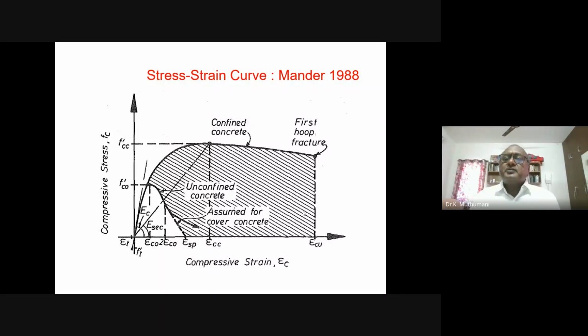And that is what is going to matter, because one thing is very clear by now, that the load that is going to come, and because of that the stress that is going to come, is larger than whatever you computed. That is the first step. The second step is, the only way of taking care of it is if the concrete has a higher strain capacity. Please understand, if the concrete has higher strain capacity, obviously this type of structure is going to survive.